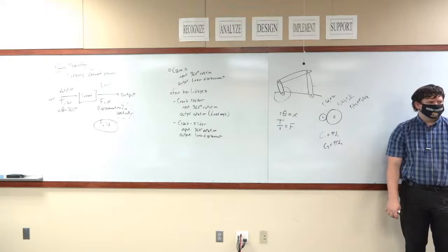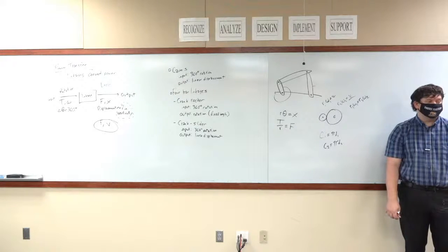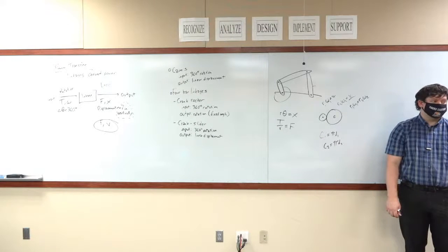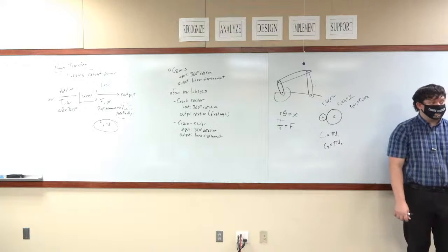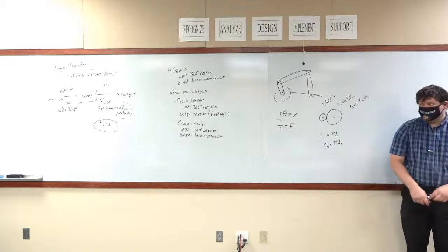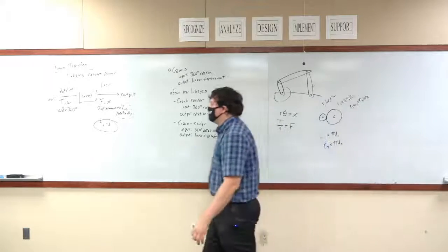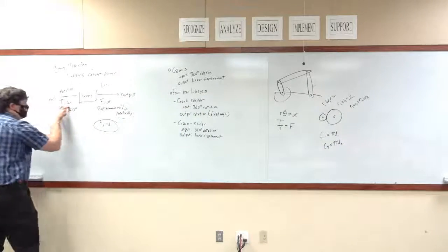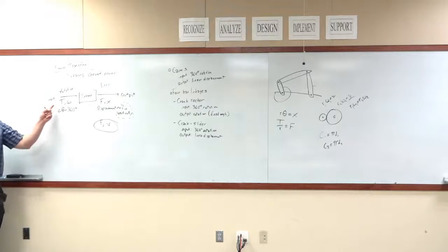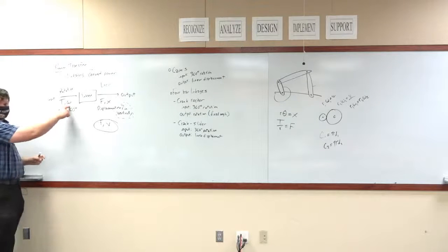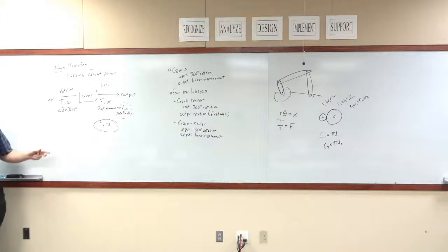You're inputting too much power to just 1 rotation. You're right. Because the idea is it's all about power transfer. These two multiplied by each other equals power. You have to put in the same amount of power to that gear system no matter what. So if you rotate it once and you're putting in, maybe 3,000 pound-inches of torque, that's the power that goes through your system.